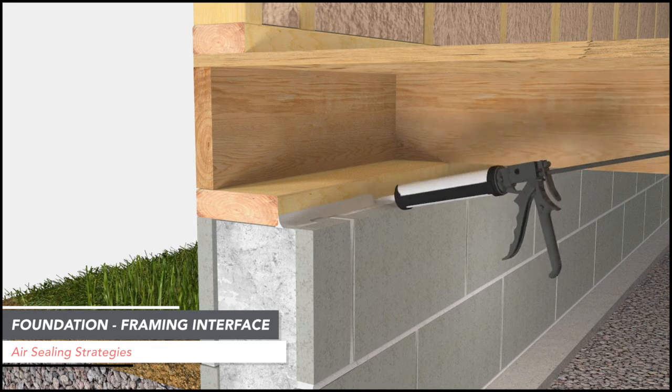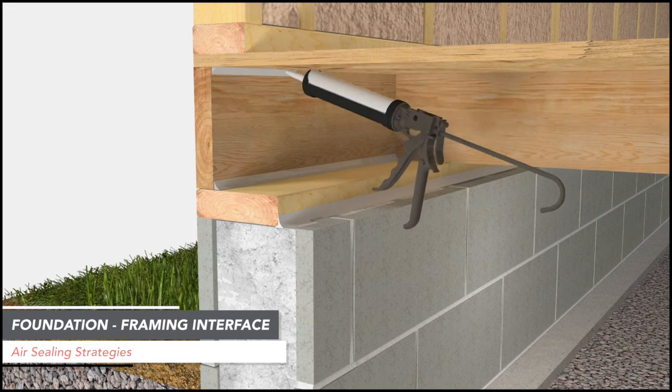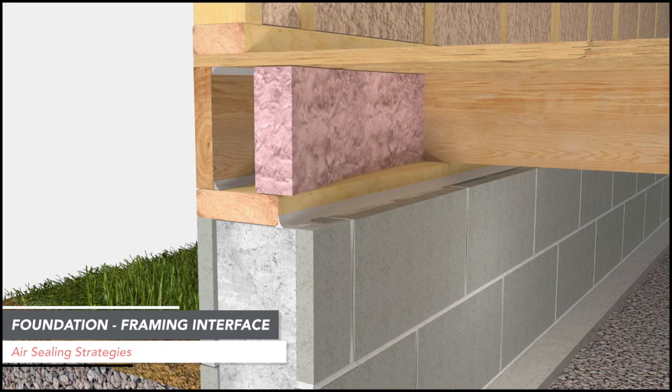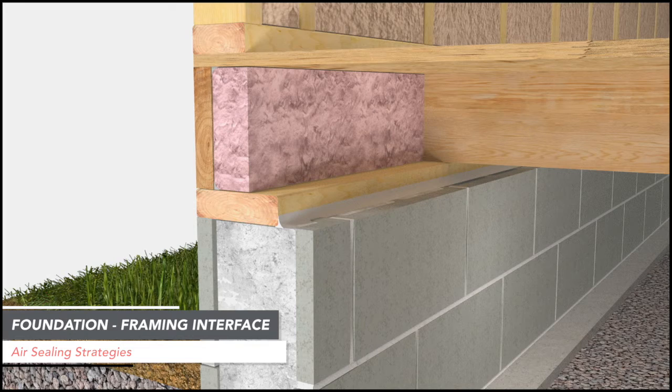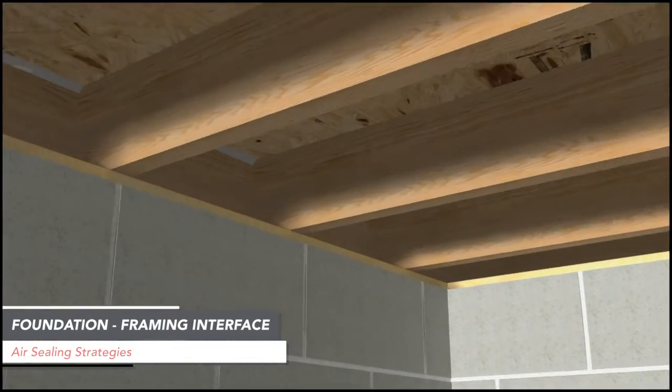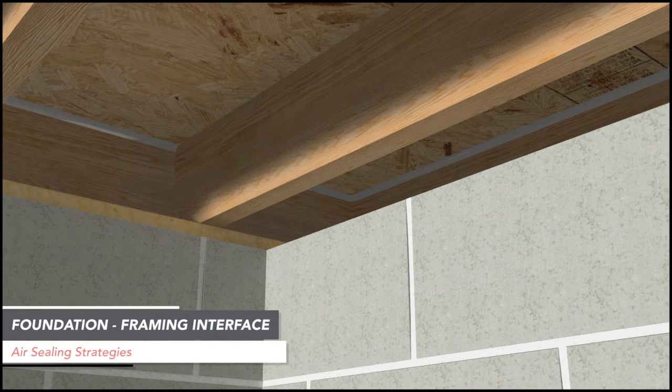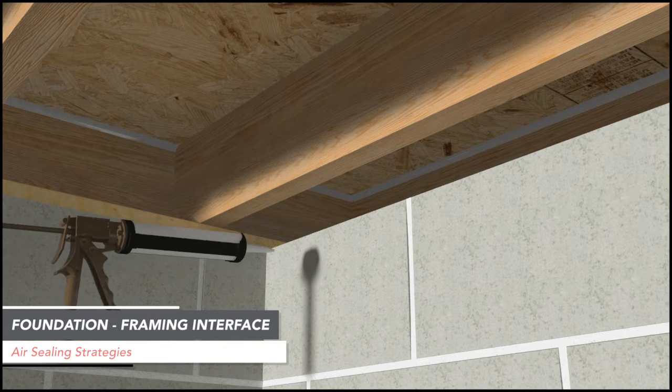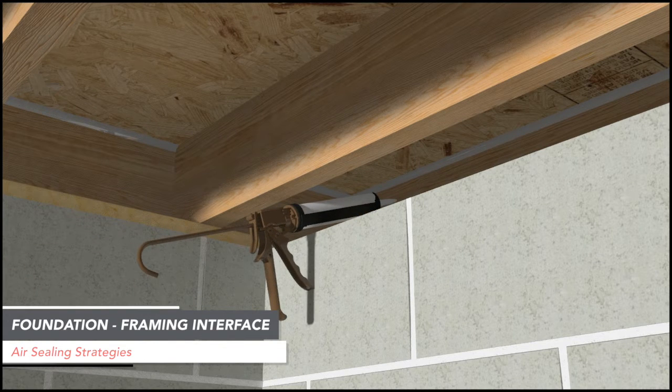One option is to seal these gaps with caulk and sealant and insulate the rim joist with a fiberglass batt. Unfortunately, the labor required to properly caulk and seal the perimeter of the rim joist between each floor joist is costly and tedious. Additionally, it may be impossible to caulk and seal the rim joist gaps where the floor joists are parallel and spaced closely to the rim joists.